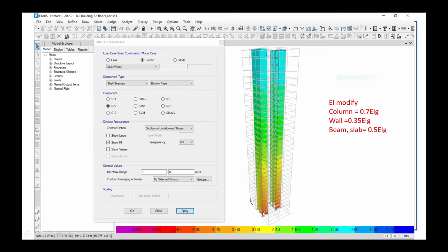We have to check the critical wall from the basement to the fourth or fifth floor. In these floors a cracked section can appear, tensile stress can appear. So you have to verify it. Now we have to verify it all. Let's check together.